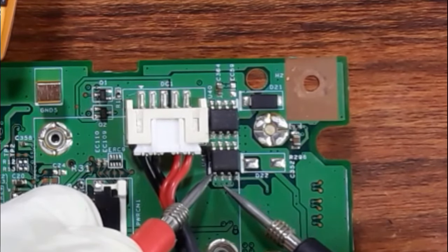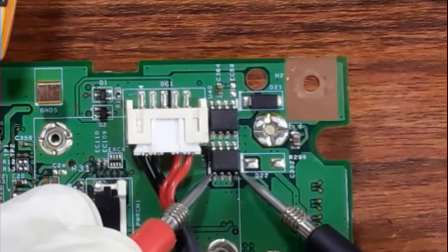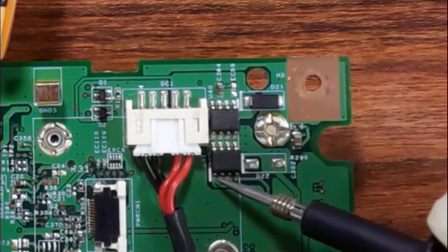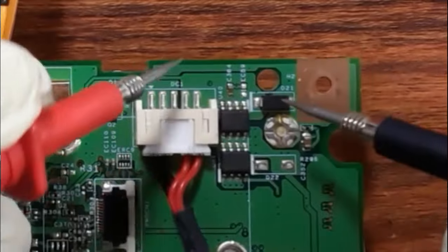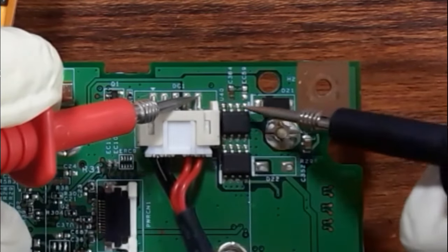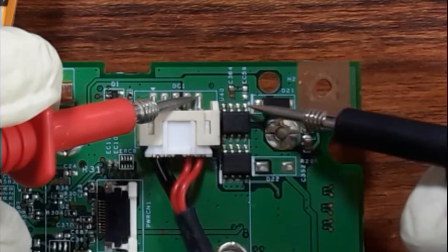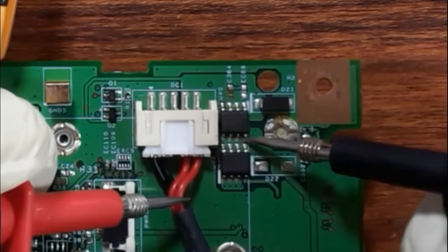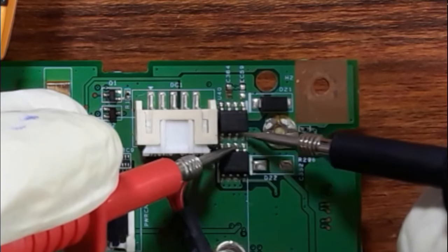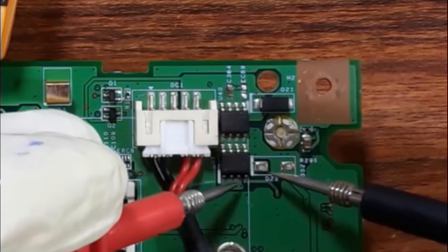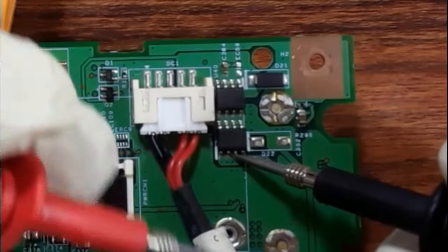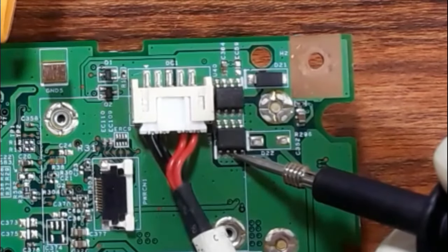I have here the second pin, the third pin. Here we have the gate not connected to this 3 pin, so we have the drain and source. The 19 volt, or the positive terminal, is connected to the source of this MOSFET, and then the drain of this MOSFET is connected to the drain of the second MOSFET, as you can see. Then the source of this MOSFET will distribute the power through the whole motherboard.